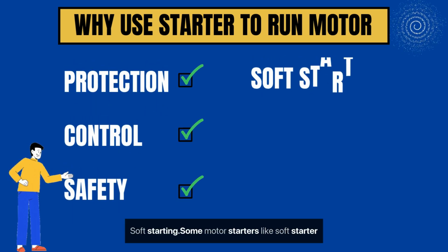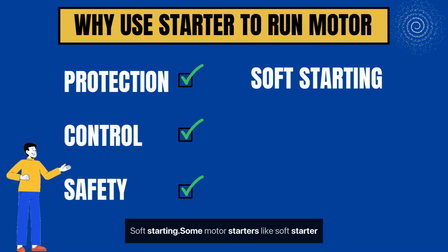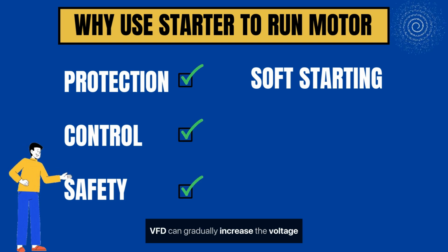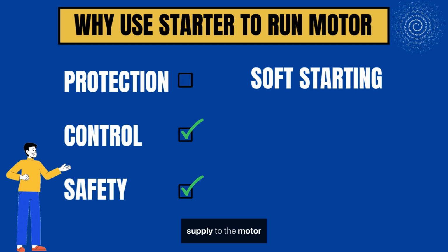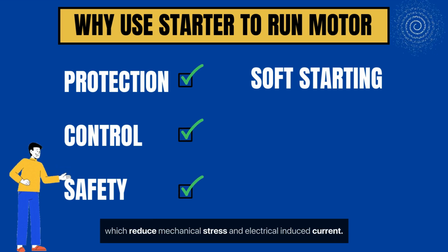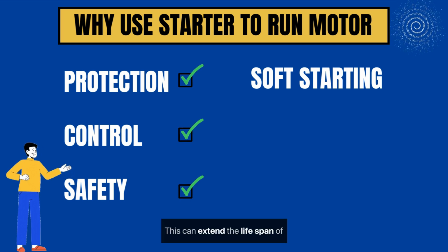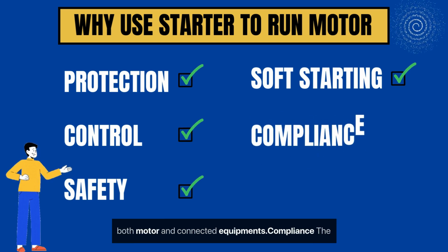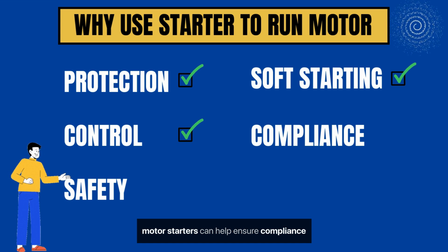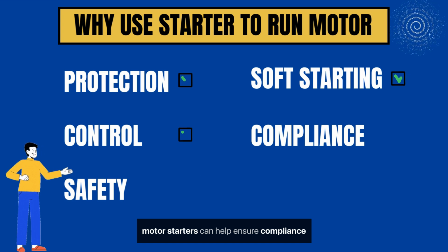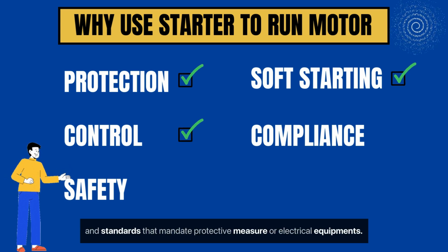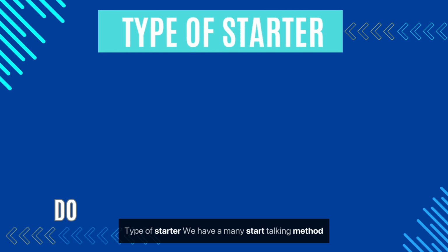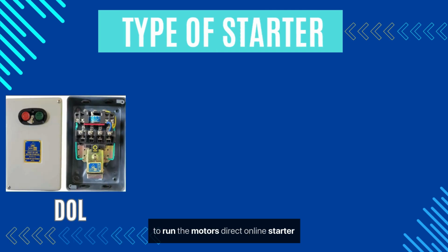Soft starting. Some motor starters, like soft starters and VFDs, can gradually increase the voltage supplied to the motor, which reduces mechanical stress and electrical inrush current. This can extend the lifespan of both the motor and connected equipment. Compliance. Motor starters can help ensure compliance with electrical codes and standards that mandate protective measures for electrical equipment. Types of starters. We have many starting methods to run motors.